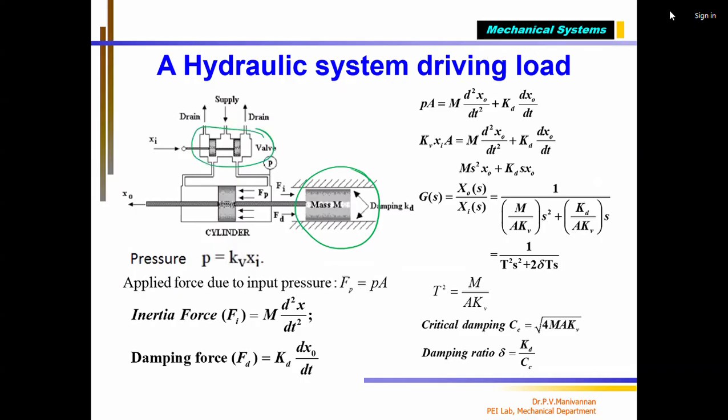What I saw previously, again the same power cylinder. Only thing is I added mass. And also, as you told, now you can see that I added damping also. Correct? Okay. It is moving with this one. The mass is moving inside a cylinder, and there's a friction in the valve. Correct? So that is what we call damping. Friction is called damping.